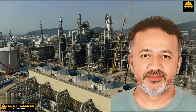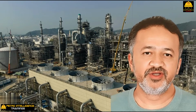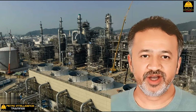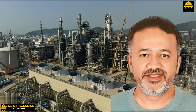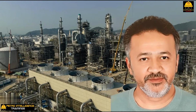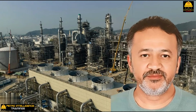Fin fouling. In a forced draft air cooler, cool air is blown through the underside of the fin tube bundle. In an induced draft air cooler, cool air is drawn through the underside of the fin tubes. Either way, road dust, dead moths, catalyst fines, and greasy dirt accumulate along the lower row of tubes. As the tubes foul, they offer more resistance to the airflow.